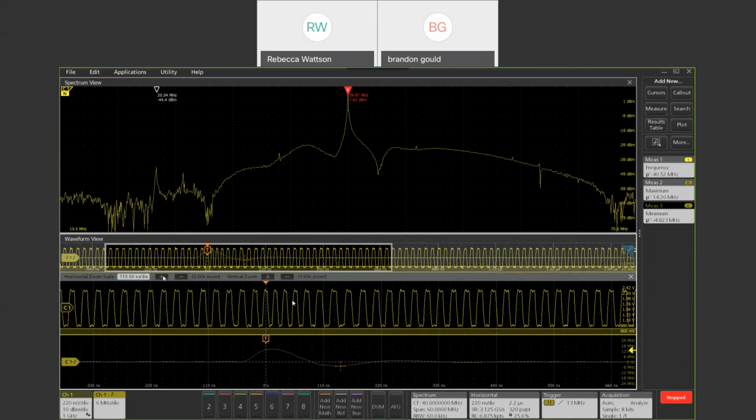This is something I would have missed in the time domain if I wasn't able to trigger on and completely isolate these deviations in my clock. So that shows the power of having a hardware-based RF versus time trigger. You can trigger on rising edges, falling edges, pulse width, timeout events, many of the standard signal types that we're used to as analog circuit designers.